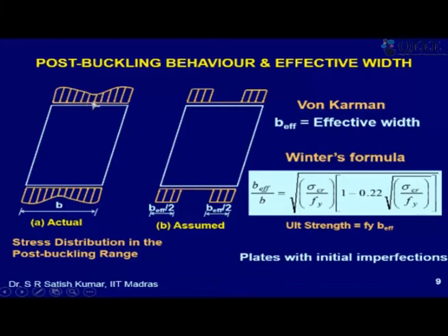So it will not take any further stress, and as a consequence, only the middle strip has buckled, but the edge strips, that is the strips next to that, are further able to take load. Okay, because these two are my longitudinal edges and they are hinged. Hinged in the sense they will not allow out of plane deformation, but they'll allow in plane deformation. Okay, so as I go on increasing the stress until these edge stresses become equal to the yield stress, this plate can continue to take further load.